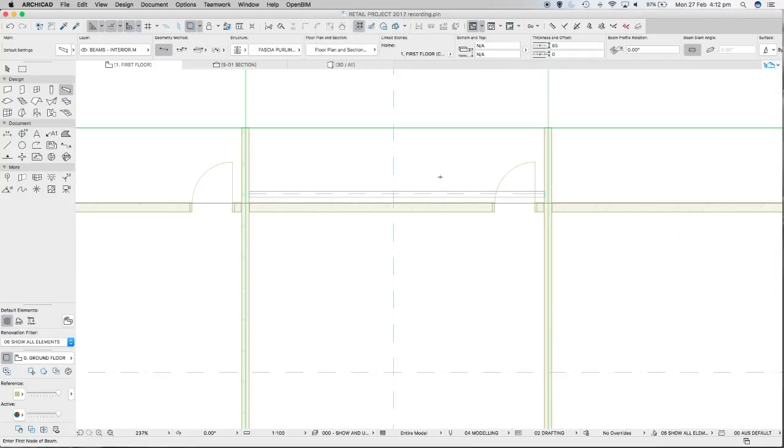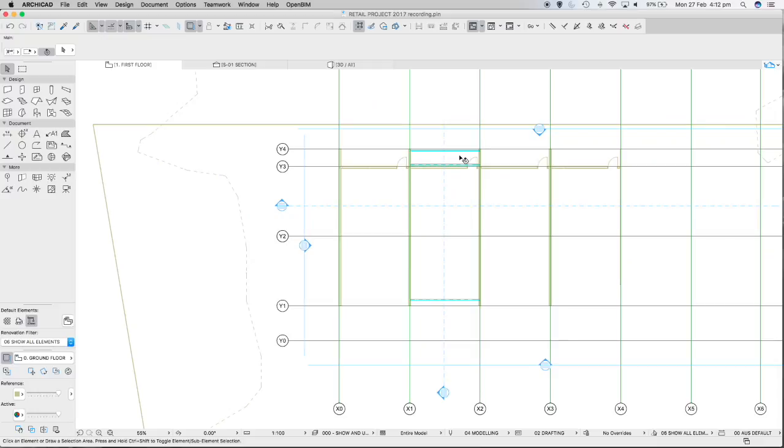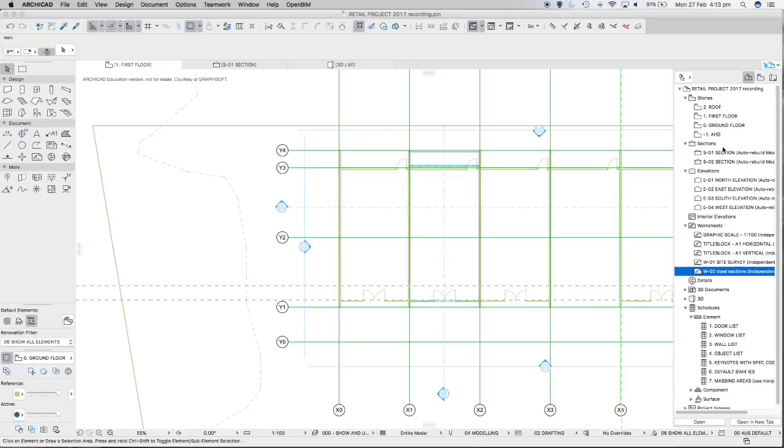And we're going to place a fascia purlin. Here's the last Z purlin that we placed before. So just place one fascia purlin on that brick wall to there. Actually, we'll probably end up sketching this all the way through the building. At the moment, we're just placing in that location. And then, like we did last time, we can then open up the section view to fine-tune that placement. So that section is hovering over at SO1. So I've got SO1 already open here. If you haven't, you can go to the pop-up and find section SO1.